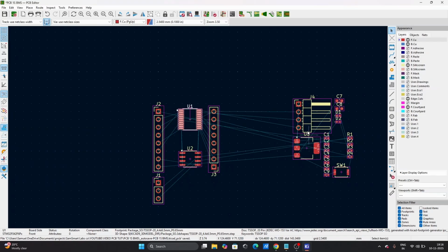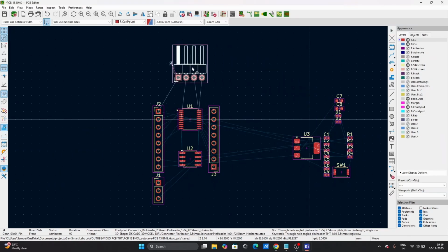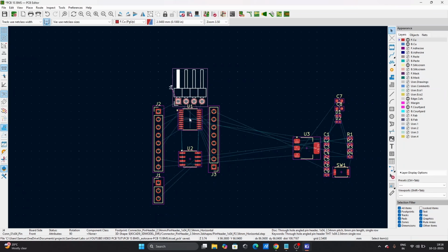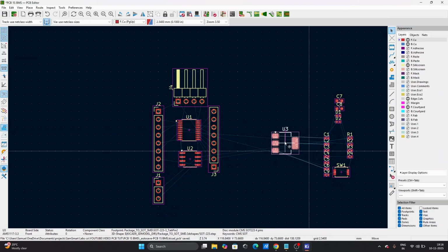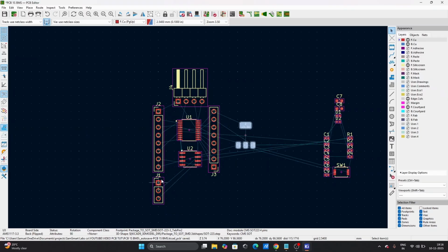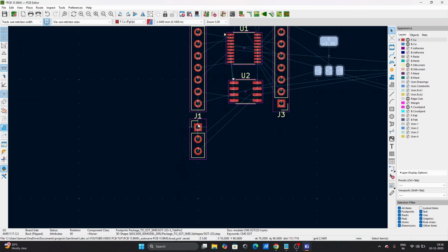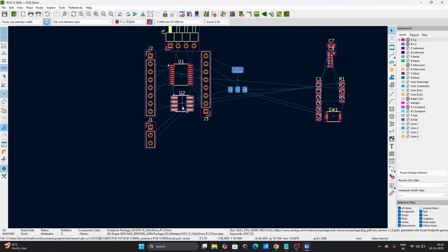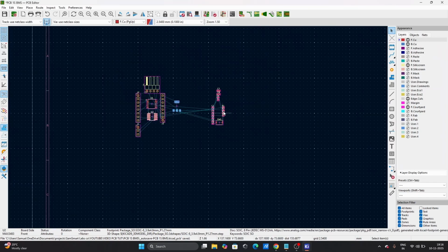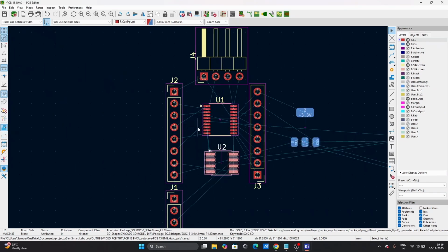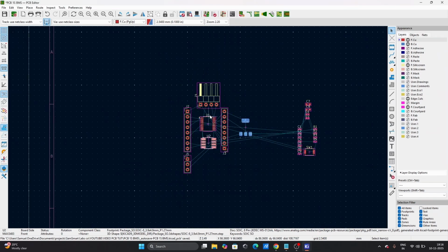Yes, I think that is pretty much enough, because then I can put the programming means ahead of here, and we can put the voltage regulator on the bottom layer. And okay, so we can work with this. I'll just bring up a few connectors here so that we can evenly have balanced connectors. I'll just bring up a few pin headers that won't have any use right now, and we'll move from there.